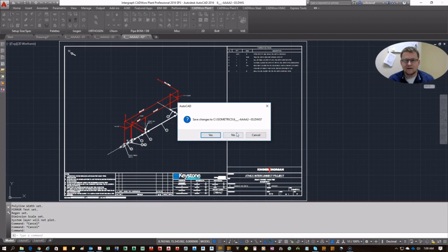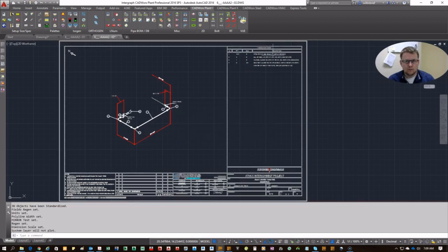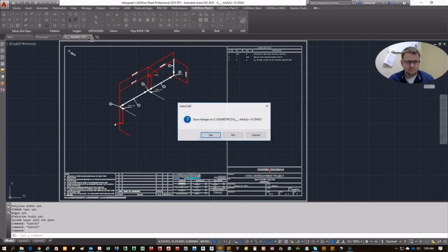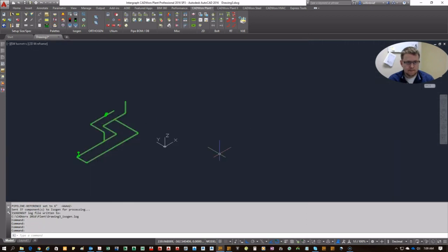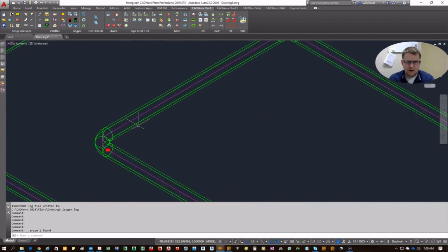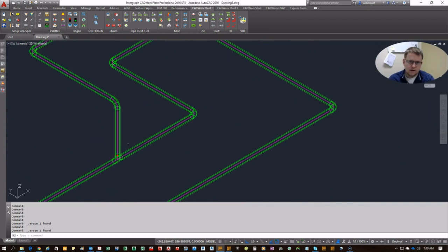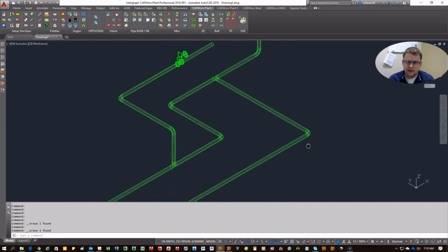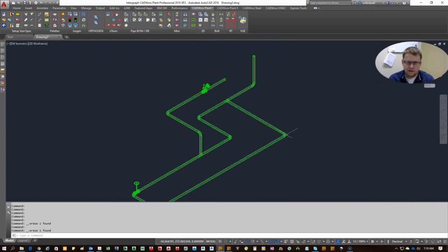So not bad. You normally want material that's going to fill up most of your bill of material, or at least half of your drawing. So these would be a little bit too small. Especially when you're dealing with pipe, because it can stretch pipe in and out pretty easily. We could probably get away with just leaving that one stop sign. Let's try again.